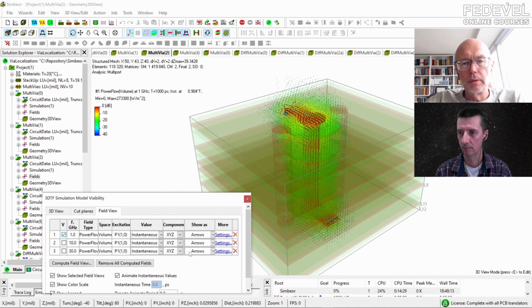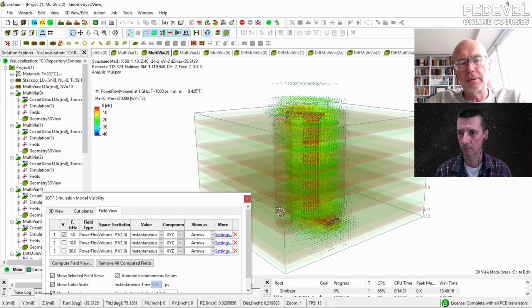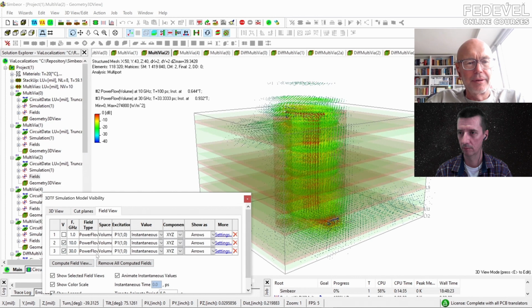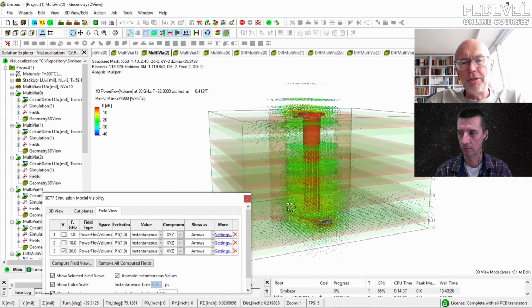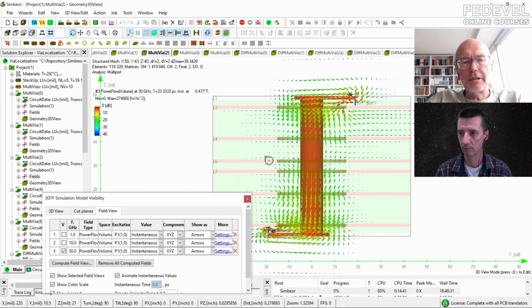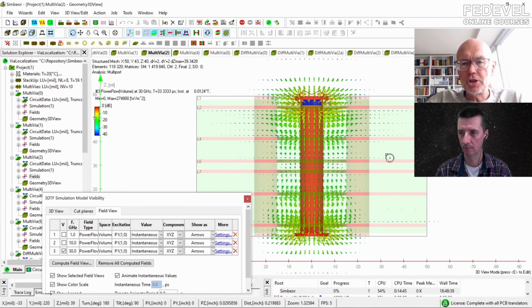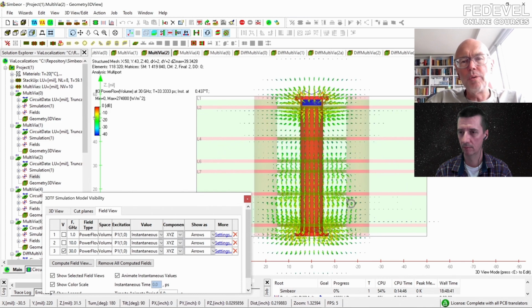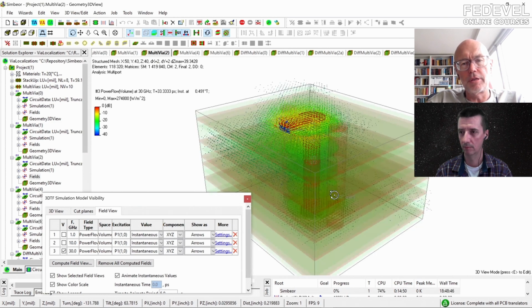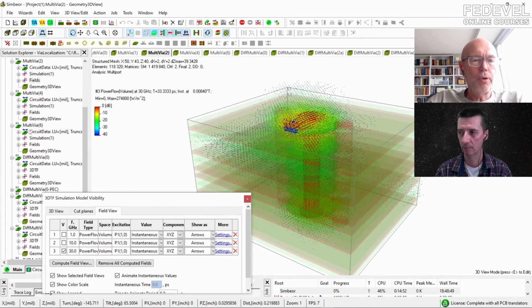Let's take a look at 2. Again, it's just a brief demo of where the signal is at 10 gigahertz and 30 gigahertz. Okay, 30. At 30, it still radiates, and you can see from the side view it radiates this way, where the vias are not placed. No vias, and at the vias, it's much smaller. Overall, much less energy dissipates at 30 gigahertz.